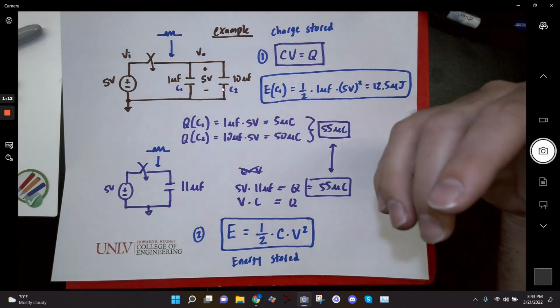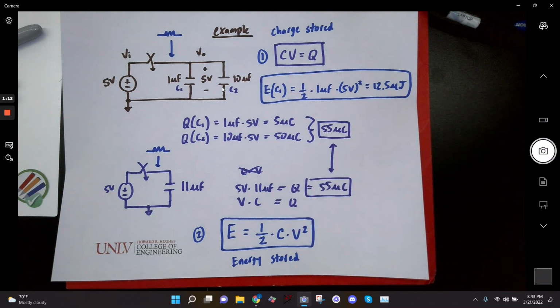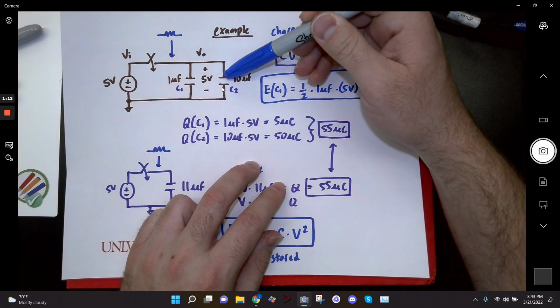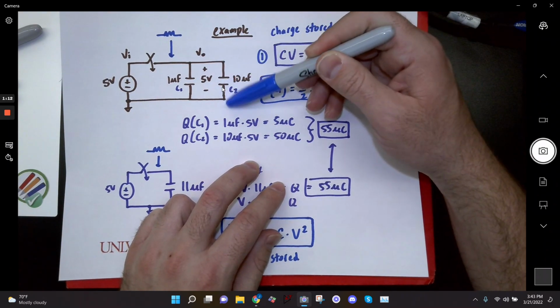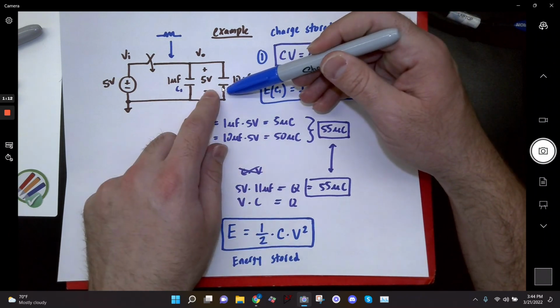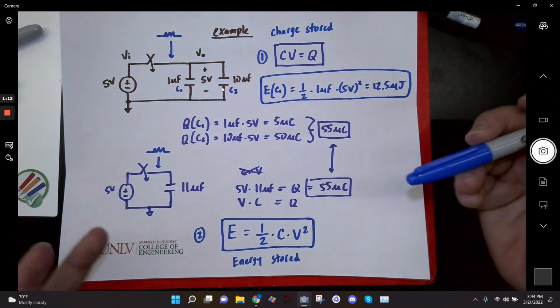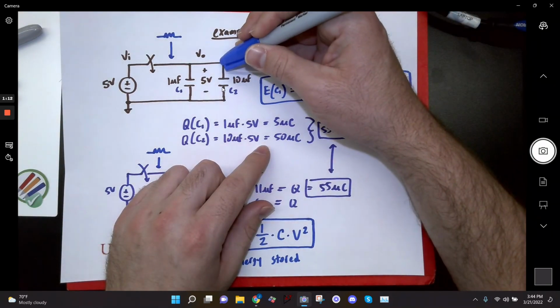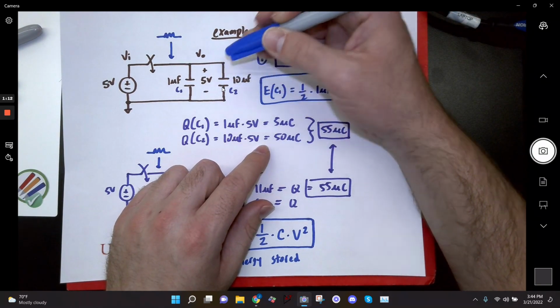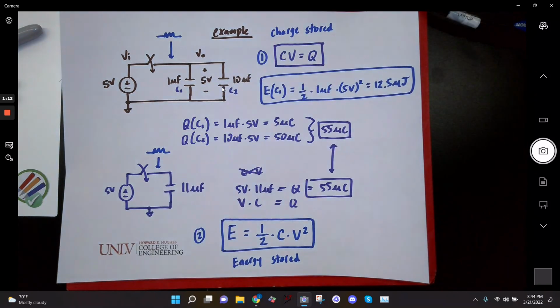But in an AC circuit, you have waves going back and forth, and the effect of that is that if I have a high voltage and then a low voltage and a high voltage and a low voltage, it induces something on the other plate of the capacitor that looks similar. And so what you get is what's called a displacement current. Charges that are displaced on this plate are basically displaced on this other plate. So you get current to flow in an AC circuit through a capacitor, but not in a DC circuit. Okay? So yeah, that's pretty much that.